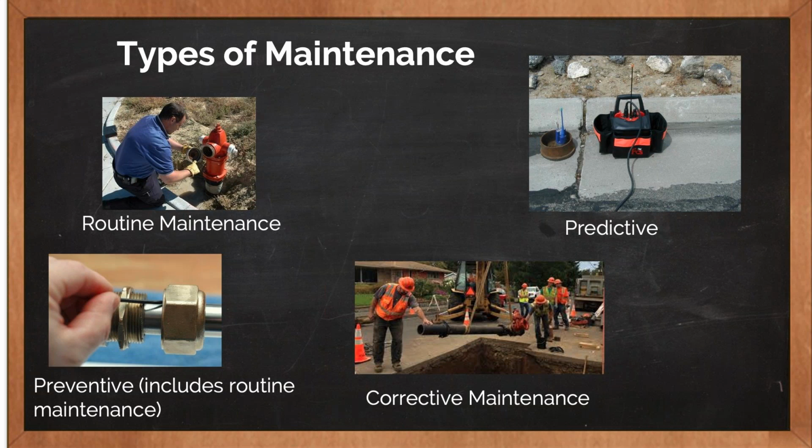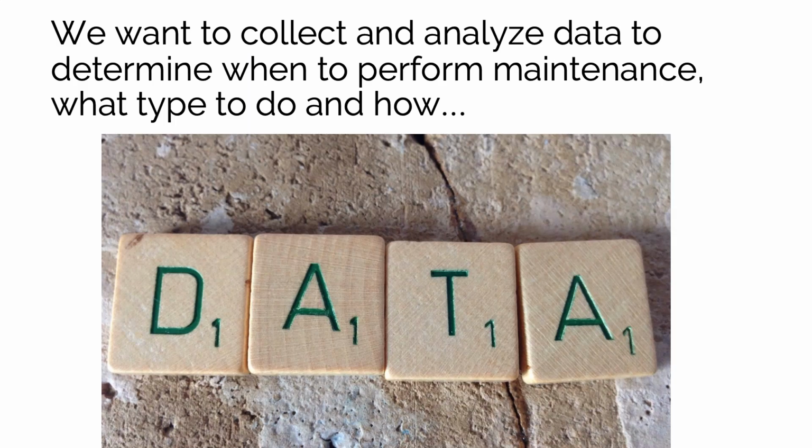You can do thermal analysis, anything like that, where it's giving you information. Even sending out the lubrication we talked about earlier is kind of predictive maintenance, because we're trying to predict, based on what comes back on the lubricant, whether the pump is okay or not, whether something is going to happen. So all of that type of stuff is predictive maintenance.